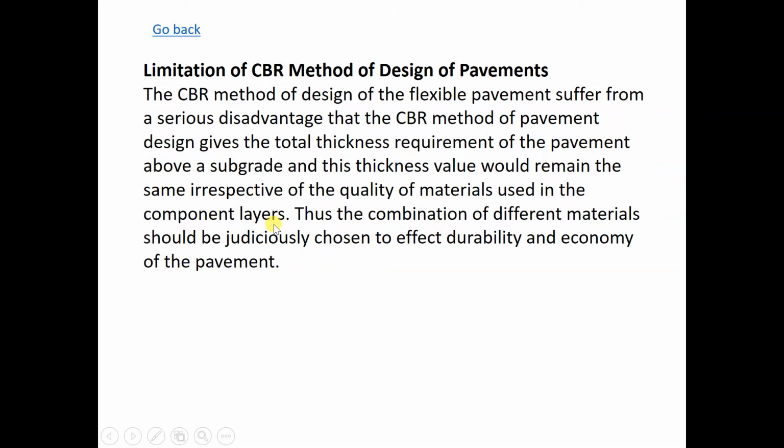Just now we looked at the chart, we just looked at the CBR, regardless of the strength of the material. That means, for example, you could be using basalt or you could be using limestone. Actually, the quality of the two is different, but they are treated the same if you can compact to, let's say, 20% CBR, 20% for the basalt and 20% for the limestone.